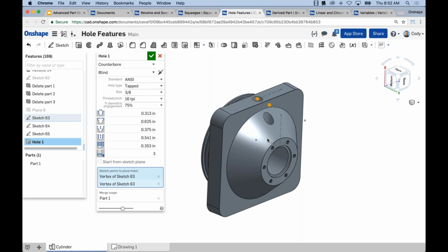There is the ability to drill holes through multiple parts. And with multi-part studios, it's a really big, powerful feature. You don't have to manually line holes up. And then you would get that with blind in last. So just a tip, if you're doing holes through multiple parts, you want to end it in one of the parts, you can do a blind in last.